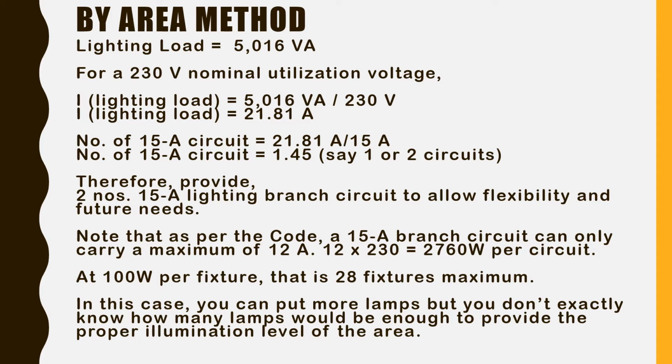This is the total current of our lighting circuit, the total lighting load. So for the number of 15 ampere circuits, we will use 15 ampere as a standard by the National Electrical Code or the Philippine Electrical Code. So 21.81 divided by a 15 ampere circuit, the number of 15 ampere circuits will be 1.45.